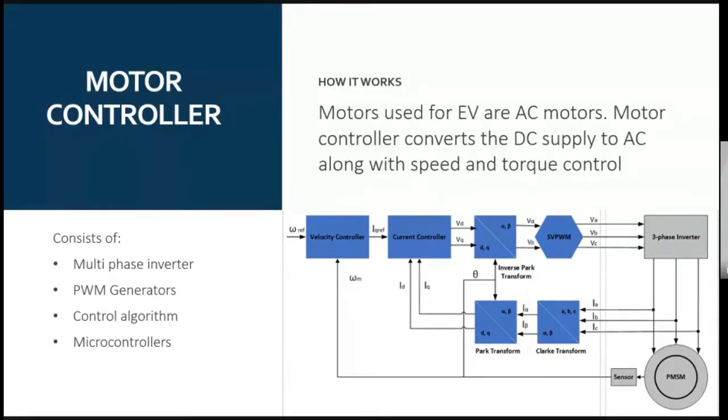Different controllers that are tuned for motor control applications are available in the market. For driving a three-phase inverter, there should be 6 pulses, and the 6 pulses should be synchronized. That means all 6 pulses should be generated from one PWM module. That can be called motor control PWM.